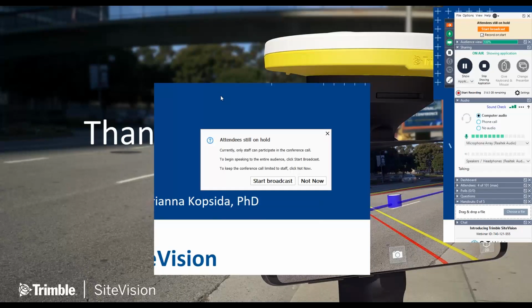If we already have a Trimble VRS subscription with other GNSS equipment, can that be used with a Catalyst to provide network RTK corrections? Yes, there's two ways you can get the corrections into SiteVision. One is what we call the Trimble Correction Hub. This will be the default, but you can also go and configure an NTRIP stream. So you can go in and set up a different connection the normal way you would in the survey receiver. So for example, your VRS corrections and these things can be set up. So that's fully possible.